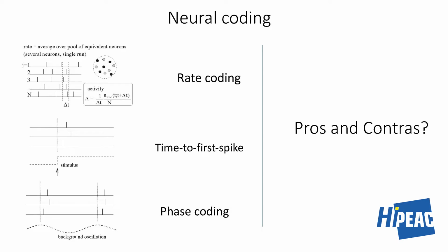So if I use rate coding and I have the number 255 that I need to represent, I have to fire, and I want to be fast, let's say, right? So I make my time step really, really tiny, and then I have to emit a ton of spikes. All these spikes will be communicated to downstream neurons, need to be integrated there, right? And then again, we have a high firing rate. So my chip will be burning. Okay, so those are some problems with rate coding.